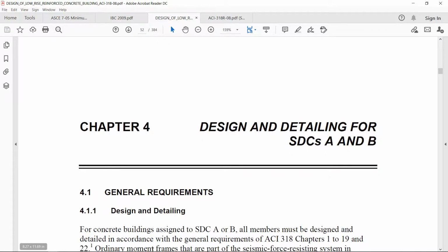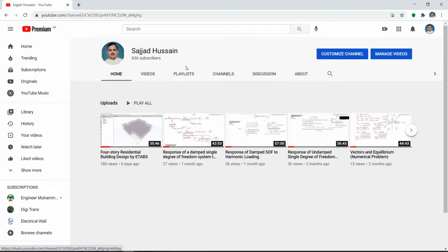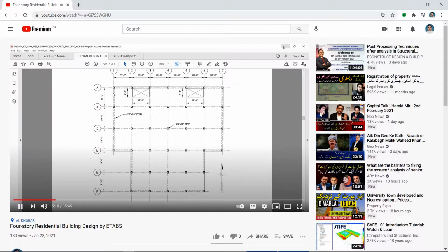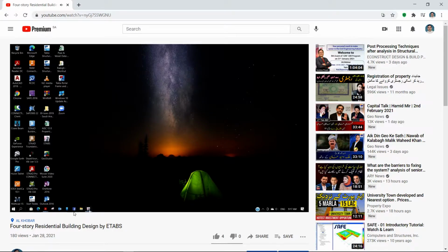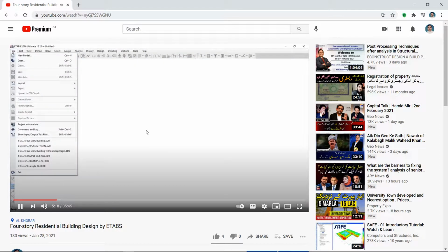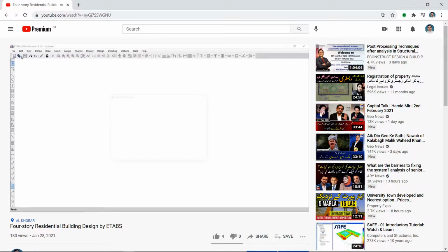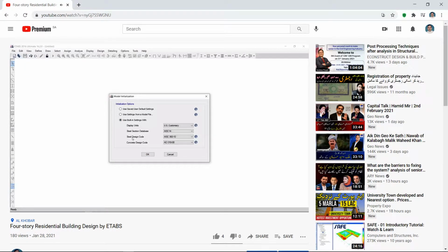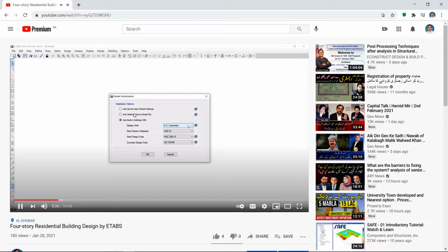Let me show you what I did in my last video. This is my channel. This is my last video, 4-story residential building designed by ETABS. So what I did, I used ETABS. So let us start this building model. The plan of the building is shown like this, and then I modeled this building in ETABS. And we will go to File, New Model. And I check the results from ETABS to the actual. Our built-in settings are units, US customary, that's correct, and concrete design code is ACI 318-08.